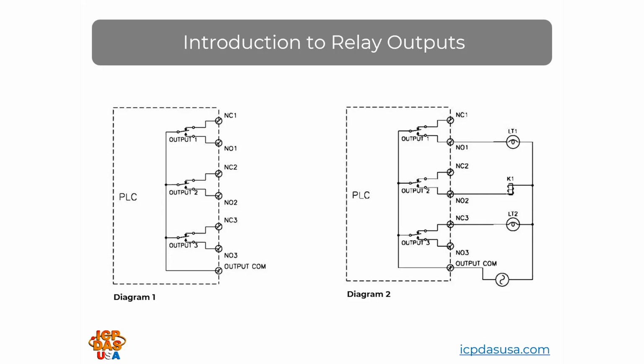In the latter diagram, in the program running in the PLC, output 3 could be programmed as an always-on coil. While the PLC is powered on and up and running, lamp LT2 will not be lit. If the PLC loses power, lamp LT2 will light up and provide the operator with an indication that the PLC had a problem. These lamps that light up based on the PLC, whether it's powered up or not, could help when troubleshooting the system and quickly show exactly what needs attention and repair.